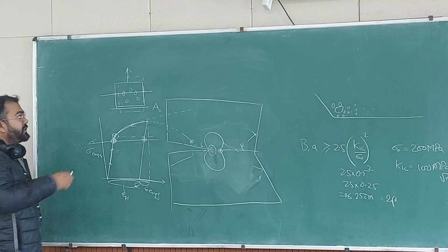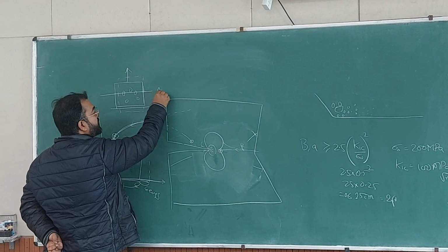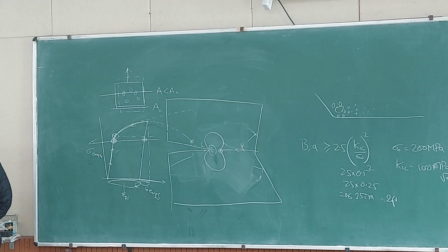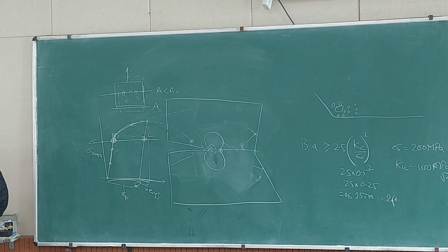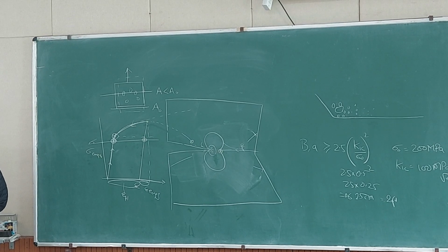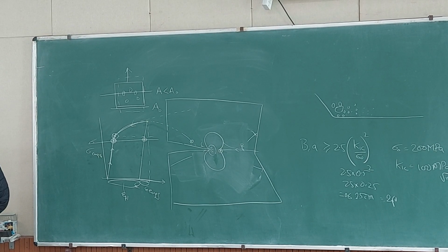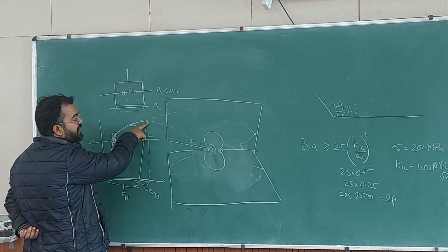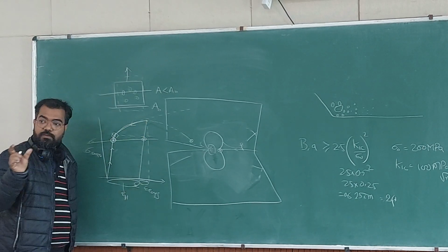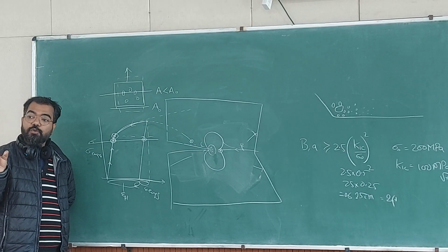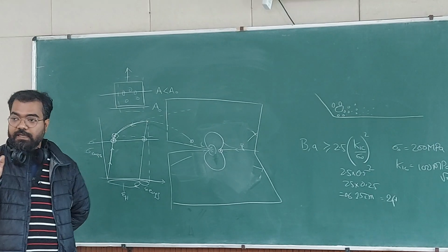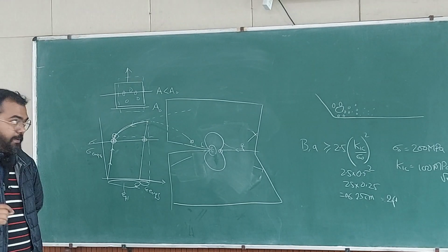When you have voids and then you cut it, then you have a different area which is smaller than A0, isn't it? Because there are voids now. Okay, it has become porous. So the area has decreased, so the stress will be increasing. Okay, so that is what is happening here. Damage is appearing also after necking, macroscopically and microscopically. In both cases, you have reduction in area, reduction in load bearing capacity.